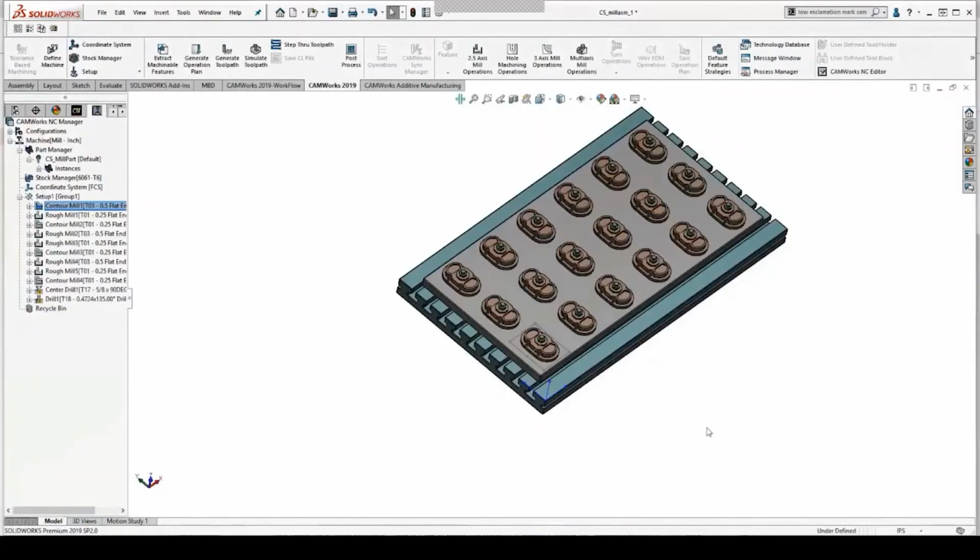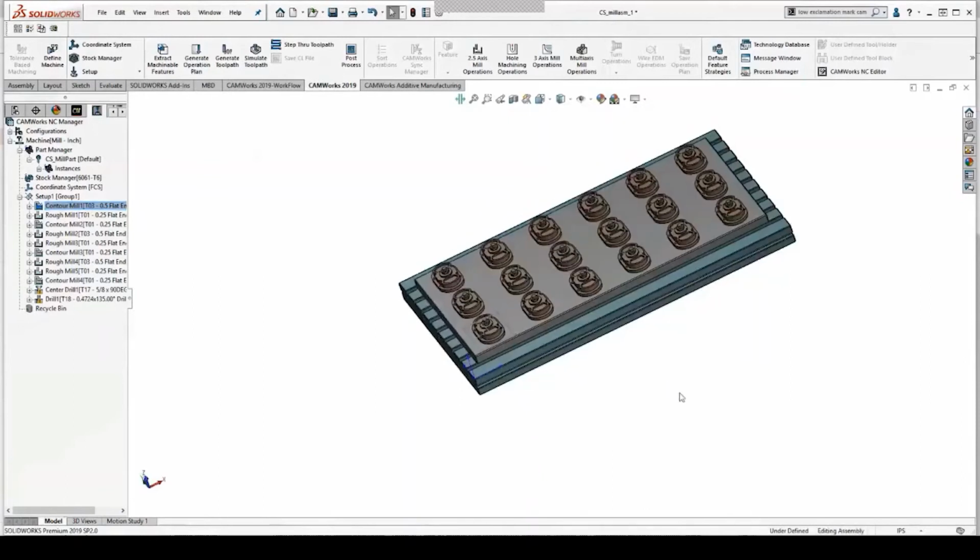You would have a hard time doing this if you're programming one part at a time and then doing a subprogram M98 to M99. That would be a nightmare, having to break down the code by tool and making sure that you have proper clearances and all of that. And much of it's handwritten. So this would be all automatically generated with the post-process button right here, and you would have your tools or your features processed first coming across as opposed to finishing one part at a time.